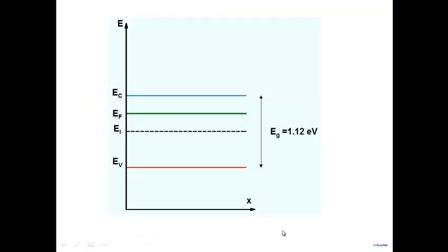All right. So here is an energy diagram that you see here, EC. Now I've drawn EF constant everywhere because it's an equilibrium. EI is here in the middle, EV is here. What type of semiconductor is it? N-type, because EF is above EI. Is there an electric field? No electric field in my system. It's N-type. Is electron density uniform? Same everywhere? Because EF minus EI is the same everywhere. So electron density is the same everywhere, right?